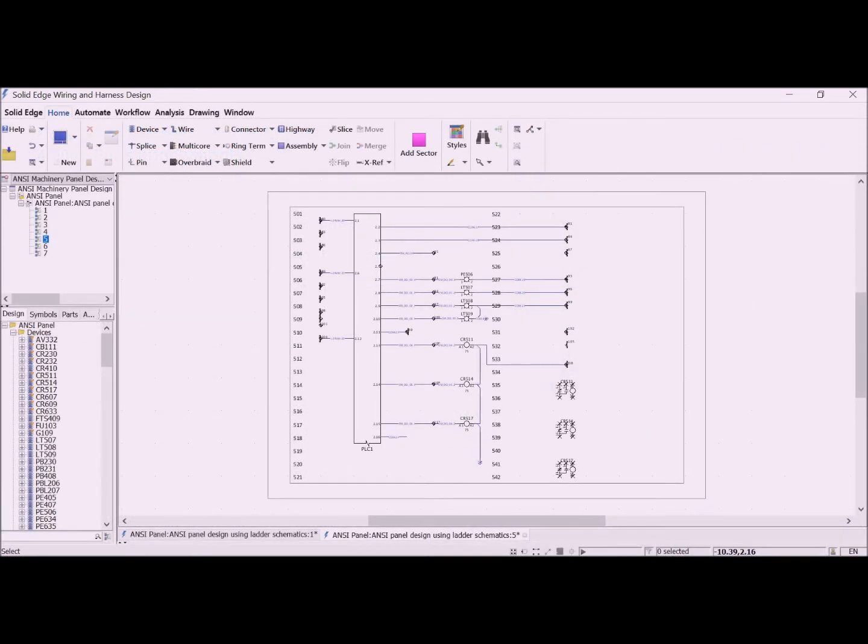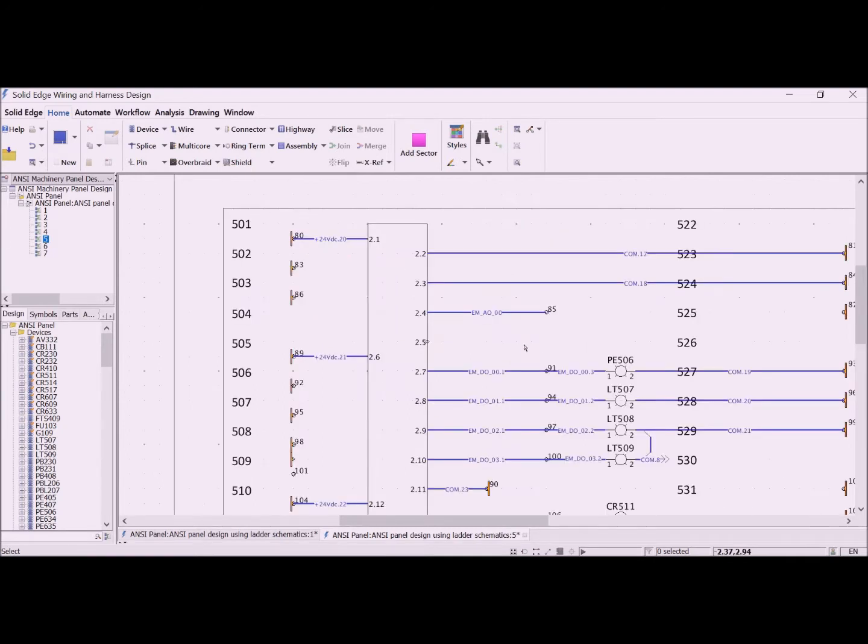Additional support has been added to the ANSI standard with the introduction of ladder diagram schematics. Here we can see a schematic that has been almost completed. The device naming is based on the ladder position, conforming to the ANSI naming convention. Ladder diagram naming is now achievable via user-defined border zones that drive the naming. The ability to control behavior via zonal areas of a product or a system is useful in applications such as industrial machinery design and panel layouts.